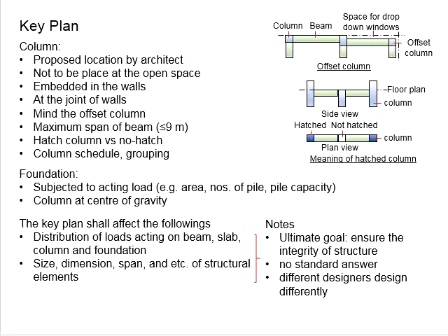This will be related to the workability of the columns, especially when you need to construct the columns. Pouring the concrete into the formworks, due to the limited space within the columns, you will have problems with the compaction of the concrete. Therefore, I would say that the smallest width for the column will be 150 mm, for it to be nicely embedded in the walls without affecting the aesthetic view of the building.